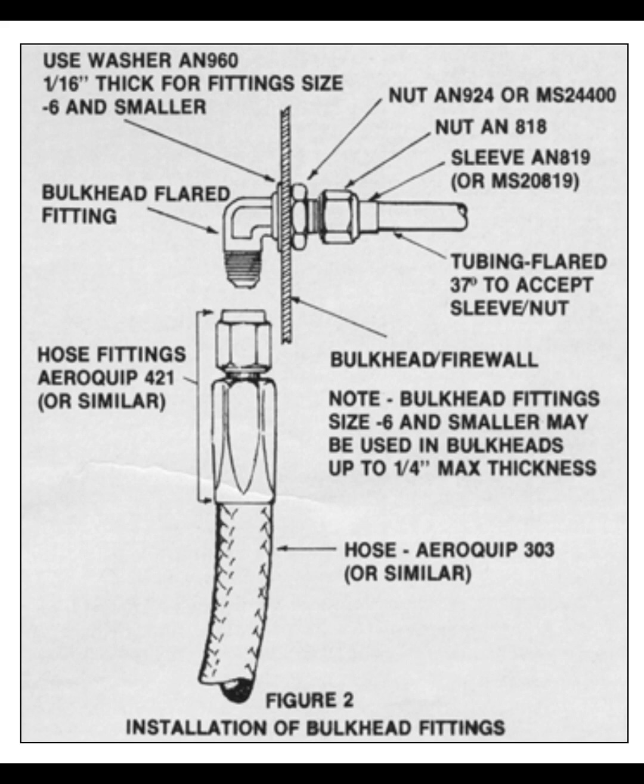What precaution should be taken when deburring and inspecting the flared end of a tube? Make sure the tubing is not cracked and the wall thickness is not reduced by the deburring process.